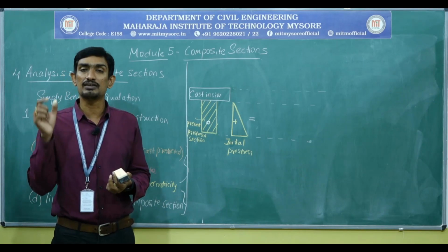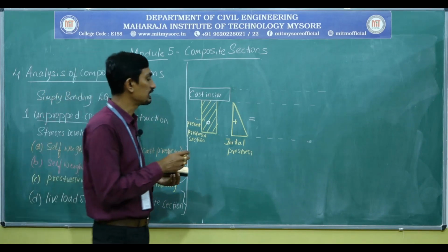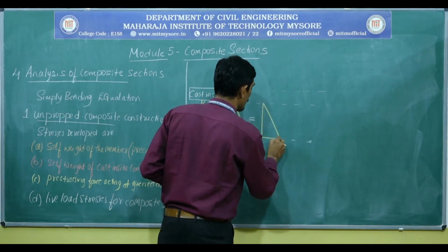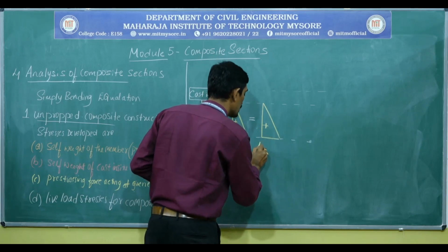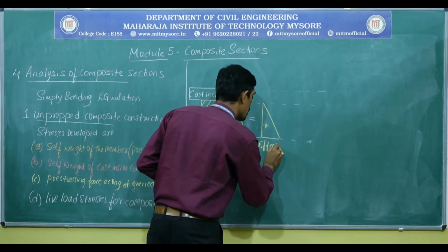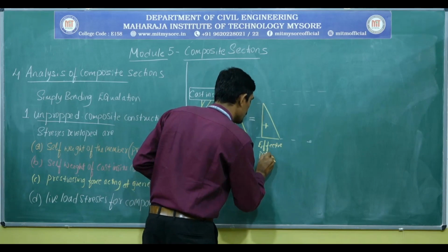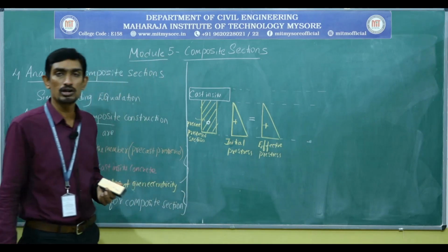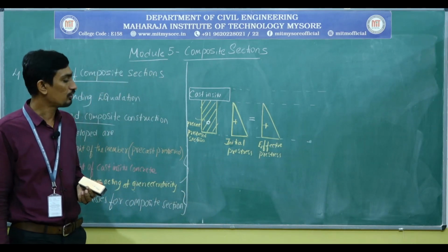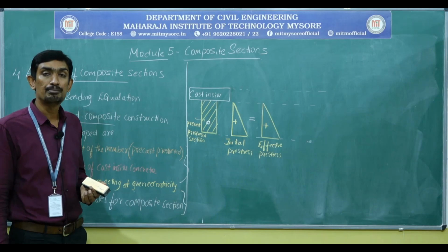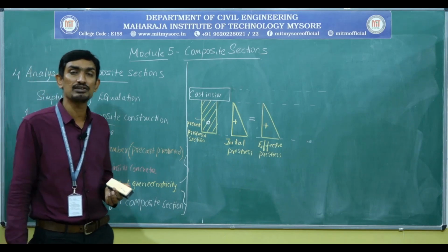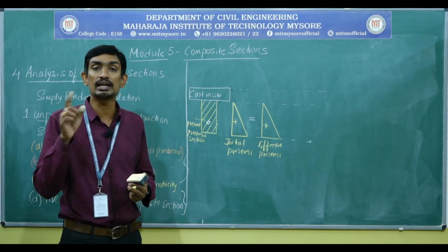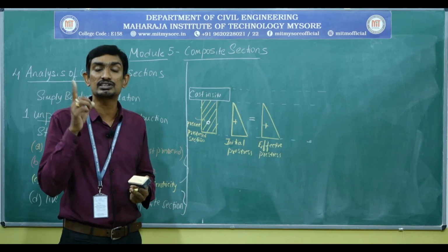Because of that effective pre-stressing force, the stresses induced will be the effective pre-stress. This is also compressive in nature. Effective pre-stress, as defined in modules 1, 3 and so on, means the net pre-stressing force available after the loss of pre-stress encountered in the precast pre-stressed section.